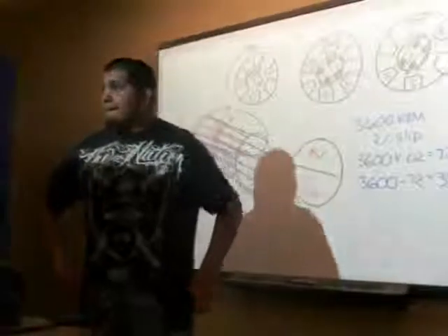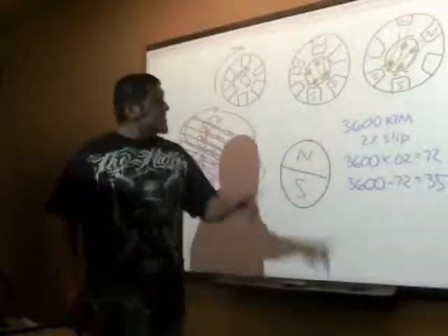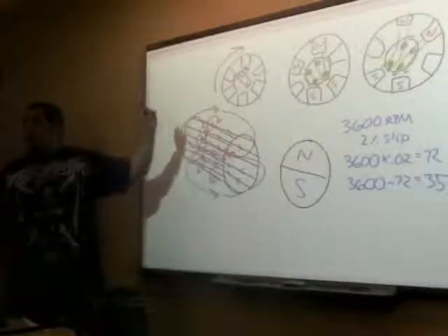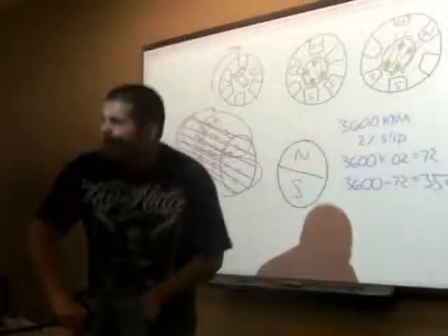All right? Startup amps kick up. Okay. So the closer we get, we lose torque. Let's say we're almost up to synchronous speed. We're cutting less lines of flux. Our magnetic fields are weaker. Then we put a load on it. What does that do? It slows it down.